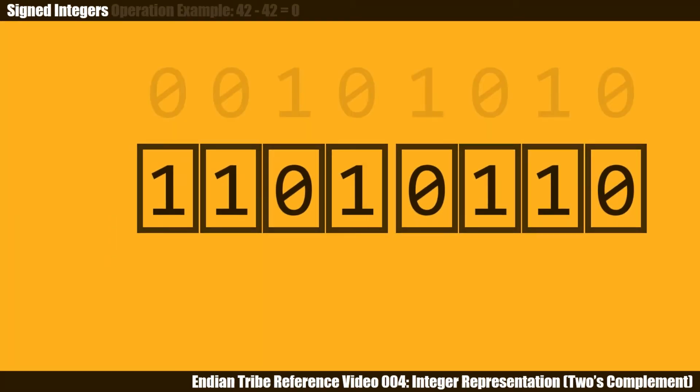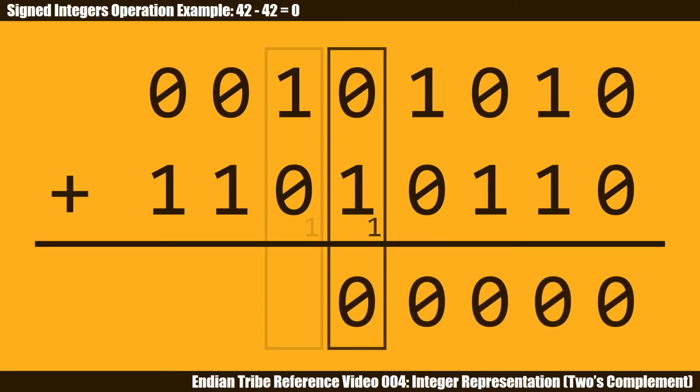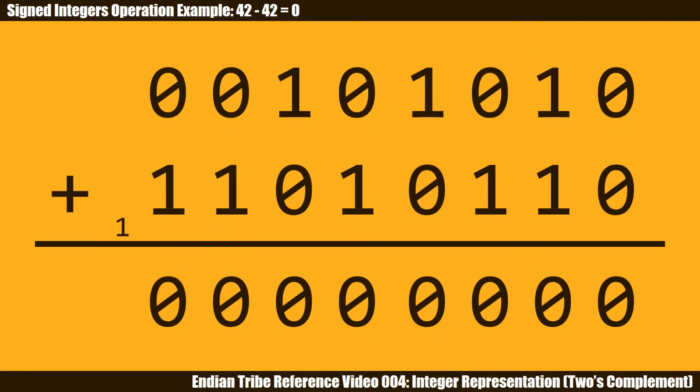Subtraction can be performed by adding the negative value. Unless actual overflow occurs, no special treatment needs to be given to any of the bits. The leading carry digit can just be safely discarded. The same circuitry that can perform additions for positive integers continues to work flawlessly on addition and subtraction of signed integers.